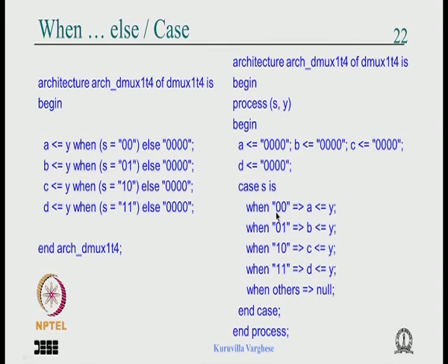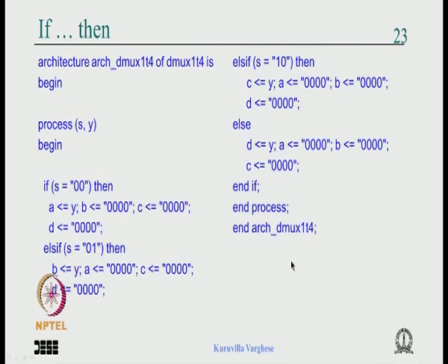Like you say if 0 0 else if 0 1, but else if 0 1 is not of 0 0, and when you make the truth table and optimize it, everything comes back to the same thing. So you could write with an if, there is no issue there because the priority will be thrown out, since all the conditions are specified, it will default to the same as before. So in principle you can write in the process instead of case, you can write if.